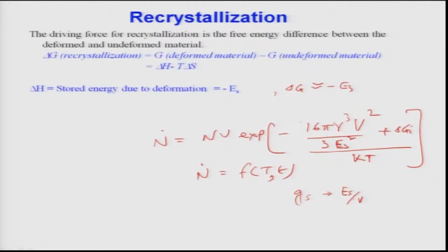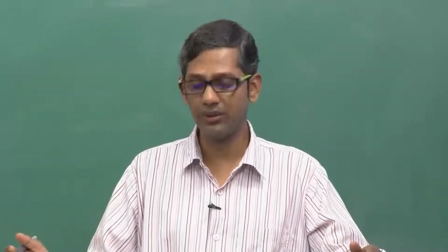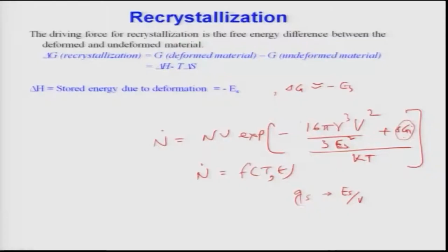this is an energy which is derived from, just a minute, let me check. Yeah. So delta G I is the activation energy for grain boundary diffusion. Yes, that is what we have been discussing. This is the activation energy for the grain boundary diffusion. So grain boundaries are moving because of the difference of dislocations on both sides of the grain boundaries, and that is what comes into the picture.